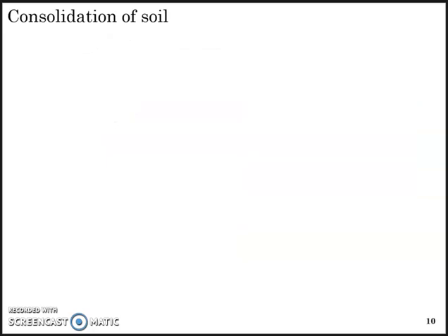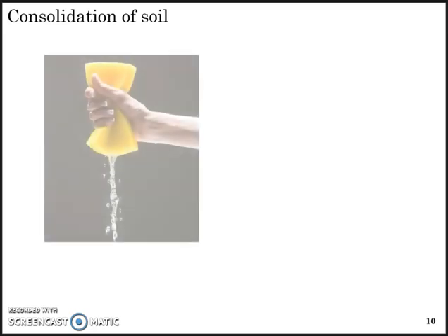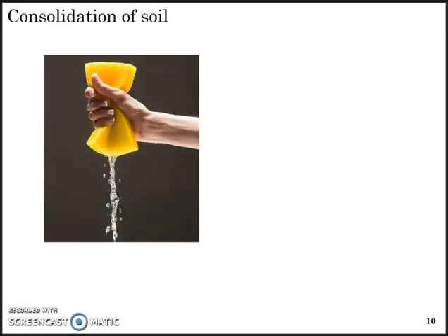Then you have what is called consolidation. Consolidation, as the name suggests, is bringing together particles. Let's take the example of a sponge dipped in water, and once you try to squeeze the sponge, water of course expels out. Quite similar to that, when you have a saturated soil and when a load is applied on a saturated soil, it behaves quite similar to that of a sponge, and water expels out.